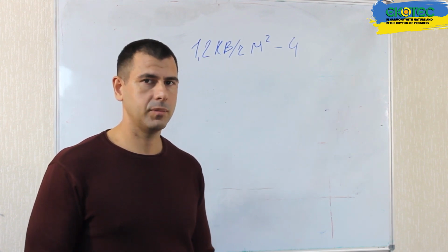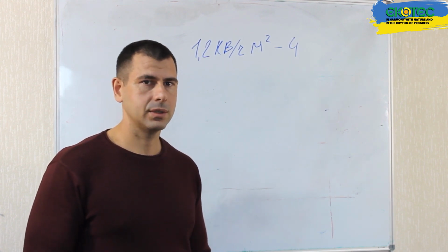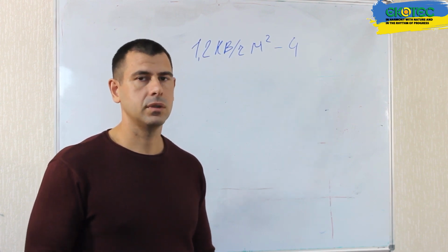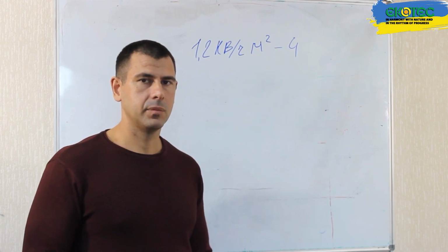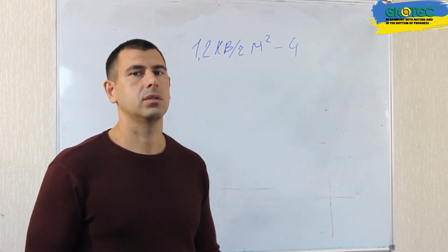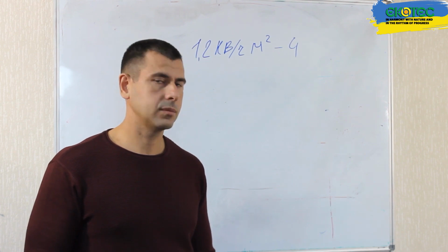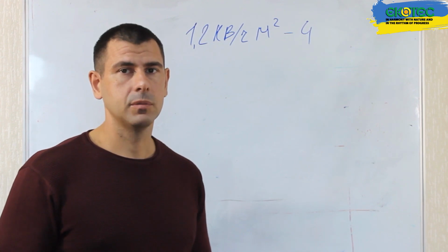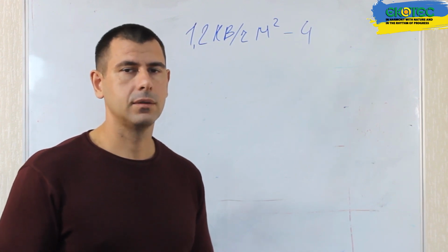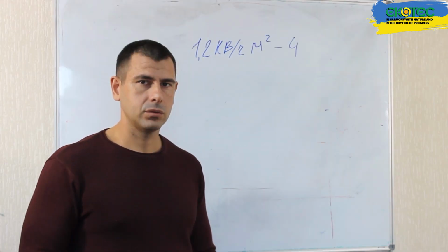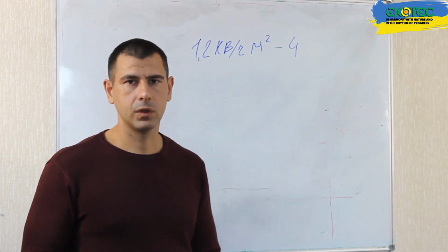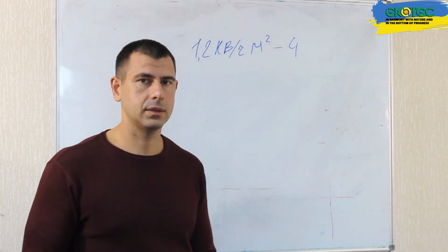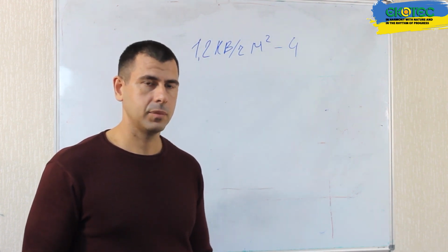If the ground and air temperatures are the same, there's no point in circulating the air. Therefore, the system operates and accumulates/releases heat for about 80% of the time. It consumes 16-20 kilowatts per day. Multiply this by days, weeks, and months, and you'll get the total electricity consumption. However, even if we assume the system operates 24 hours a day during the winter and consumes 20 kilowatts for accumulation, or even 100 kilowatts, it's still a worthwhile investment.